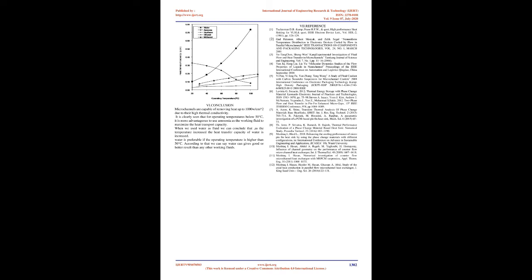It consists of the following devices: mini pump, inlet pressure gauge, inlet thermocouple, test module, outlet thermocouple, outlet pressure gauge and the fan system. First we have to turn on the heater. After turning on the heater, we have to set a measurement of current and voltage by using the multimeter. The working fluids stored in the reservoir are allowed to pass through a microchannel one by one. Then the readings are taken through a test module.